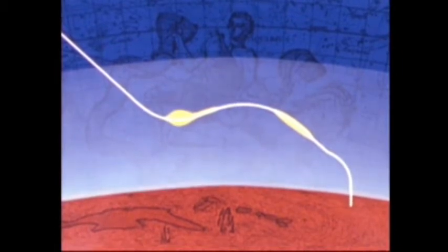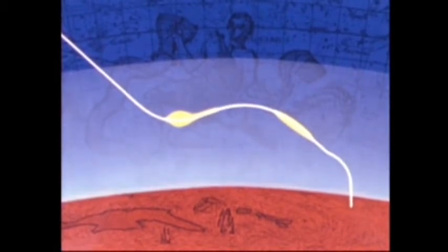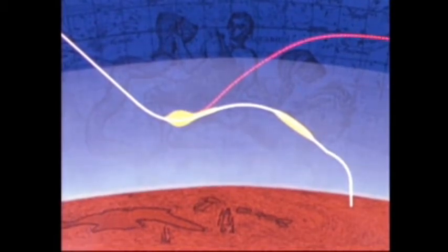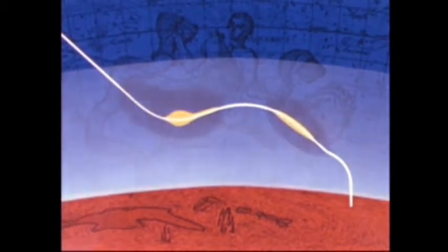For instance, an error made during the critical 70 seconds of the first control period could cause a high-speed skip, resulting in placing the command module and crew into a trajectory that would exhaust the oxygen and power supply before landing. Yet during this period, communications blackouts exist between the ground and the spacecraft, caused by the ionization of the air from the heat of entry.